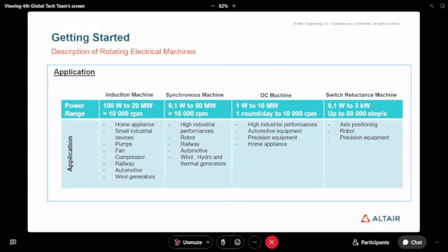They are actually between a full permanent magnet machine and a synchronous reluctance machine because we use ferrite magnet inside, and the control command is different from the permanent magnet machine because we'll see the park model of the synchronous reluctance machine is really different. Actually, it is the same, but the control angle is not in the same location.